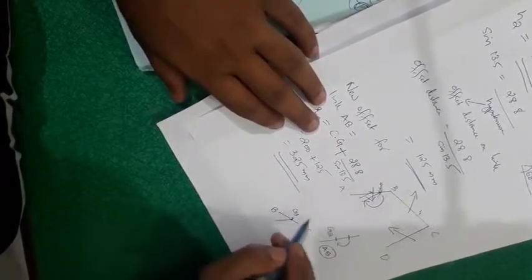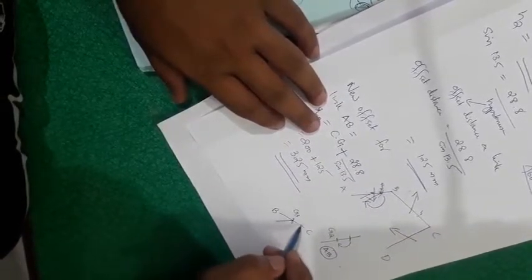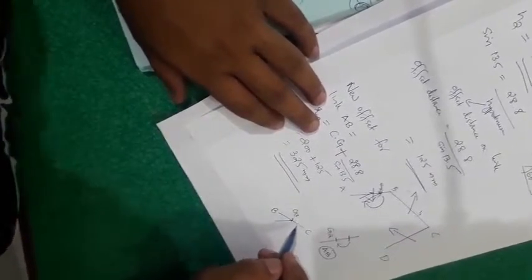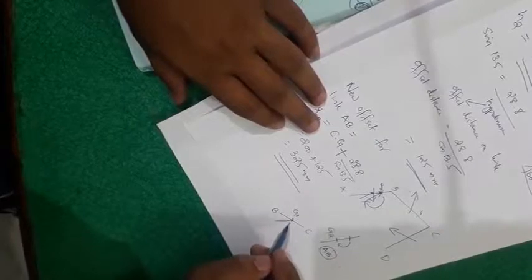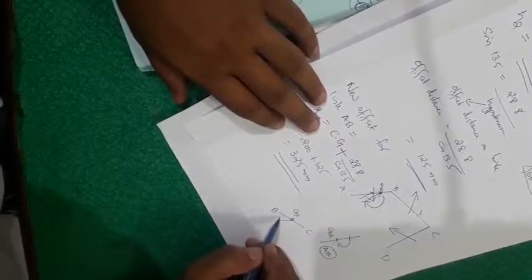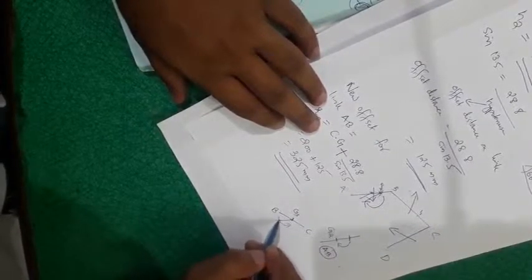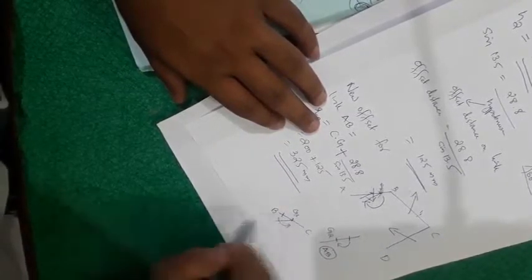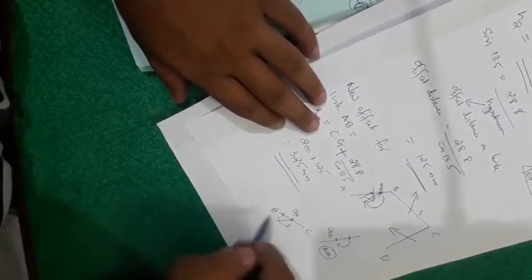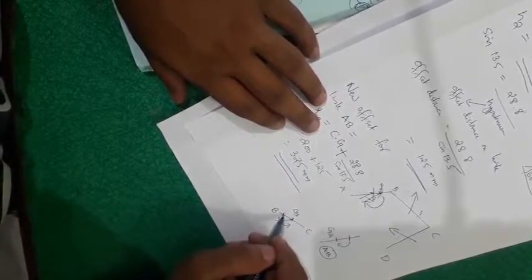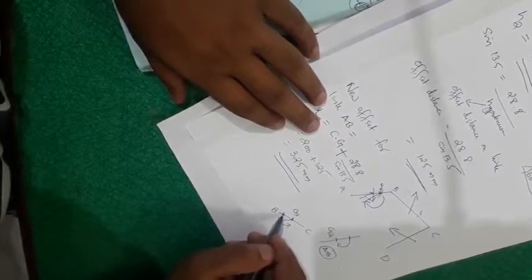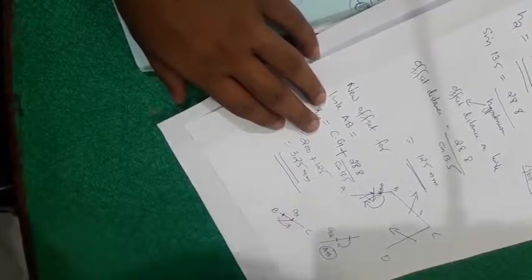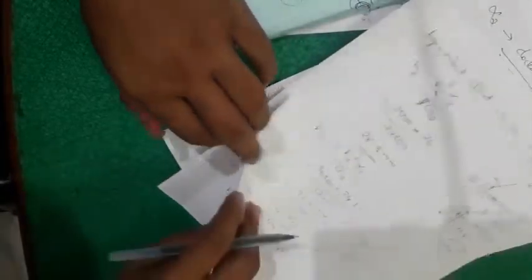So the new force should be in the anti-clockwise direction, which means it should be below G3. The original center of mass due to the inertia couple should be below G3, and it should be acting like this. We'll get to that one more time.